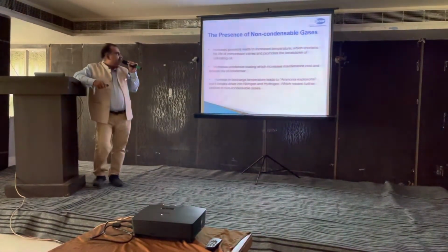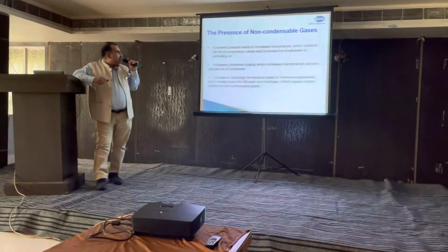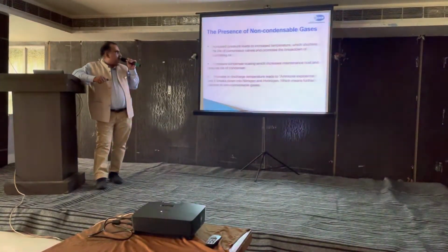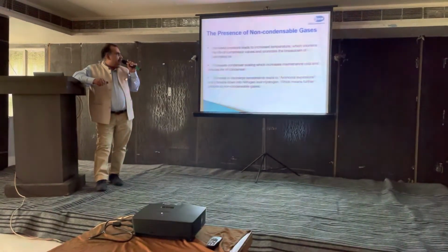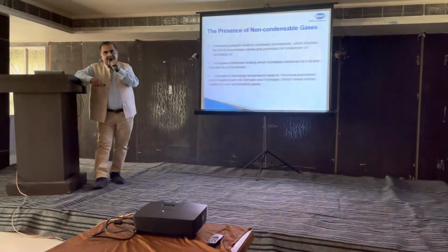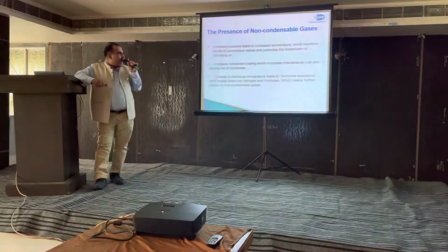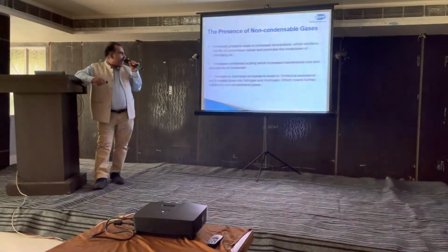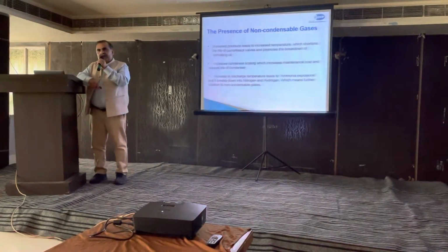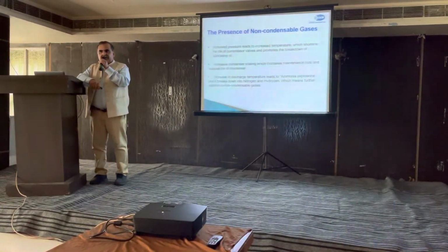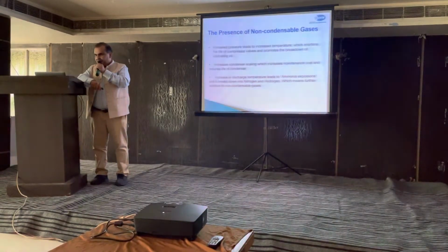Increase in pressure leads to increased temperature, which shortens the life of the compressor valves and promotes the breakdown of the compressor. There is also an increase in condenser scaling because of the higher temperature, and of course it increases the maintenance of the condenser and reduces its life. It also deteriorates or affects the performance of the condenser.